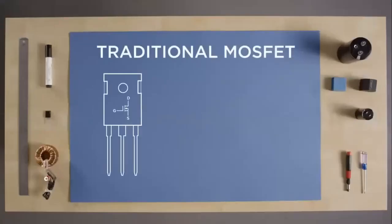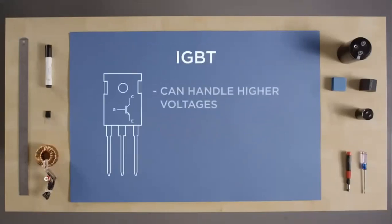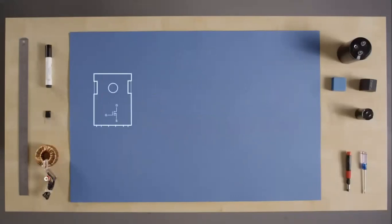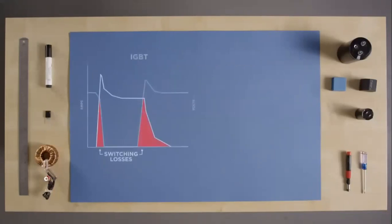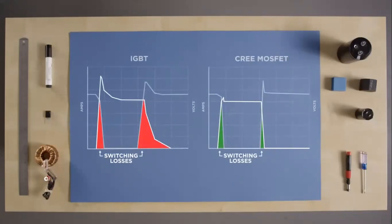Traditional MOSFETs are great because they have low switching losses, but they can't handle higher voltages, above 800 volts or so. IGBTs can handle higher voltages, but they have high switching losses. Cree's MOSFET technology marries the best of MOSFETs with some cutting-edge Cree technology that works at voltages up to 1700 volts with low switching losses. The result is that the Cree MOSFET can replace the latest generation IGBTs, but with 6 times lower switching losses.